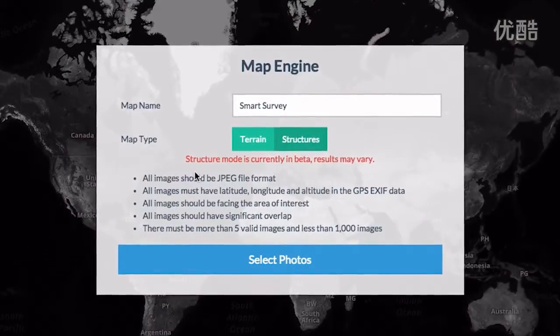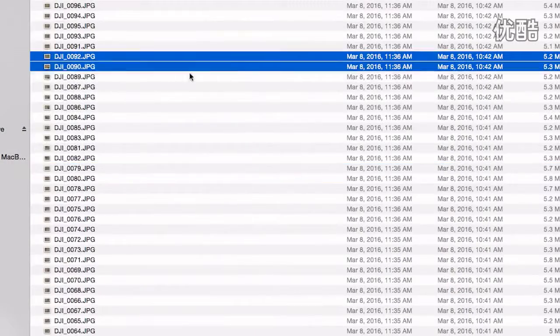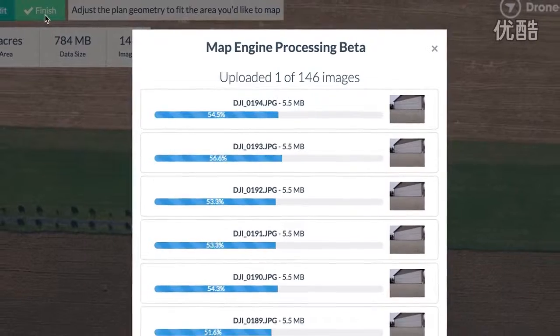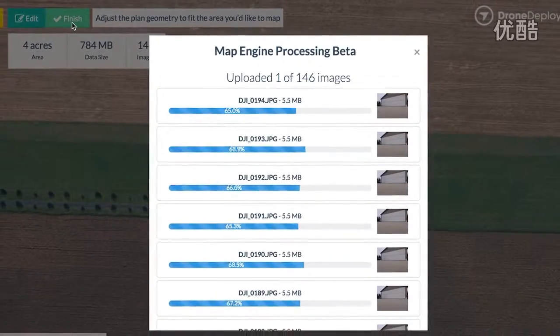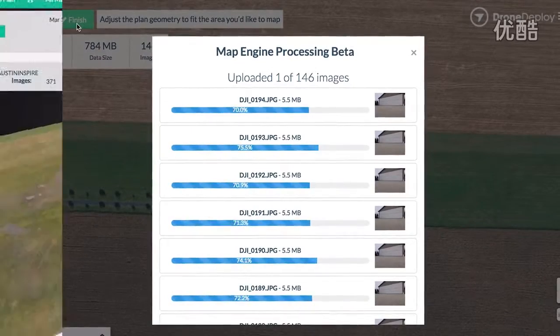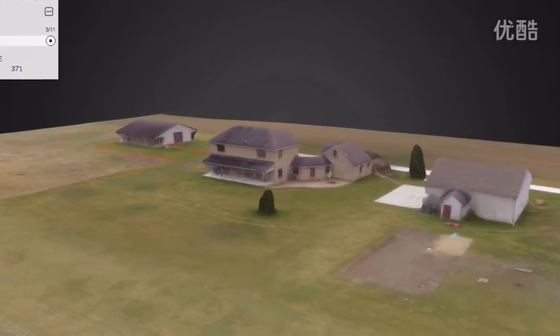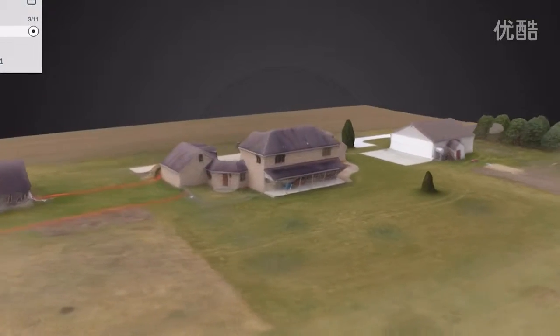Now this is a really cool thing. Even though we're exiting out of one function and going back into the DJI app, it all works within that other app, doesn't it? It doesn't change your upload at all. You basically just combine the photos of everything that you're going to upload, and you upload it all together. Because those JPEGs are geotagged, Drone Deploy servers are able to parse the differences and stitch them together in a way that makes sense. Keep in mind, it's going to be about 60 seconds per picture. So if you have 1,000 pictures, it's about 1,000 minutes. Yep, absolutely. And actually, I think 1,000 is the limit for the amount of pictures you're able to do at once.